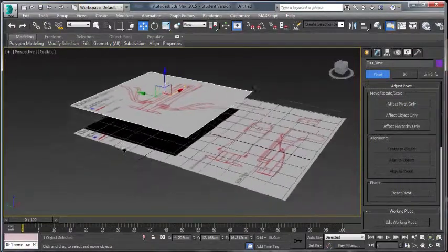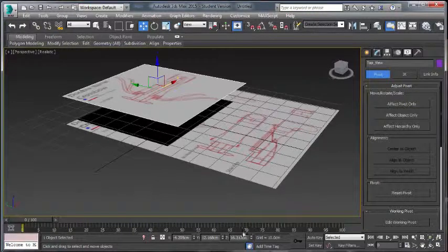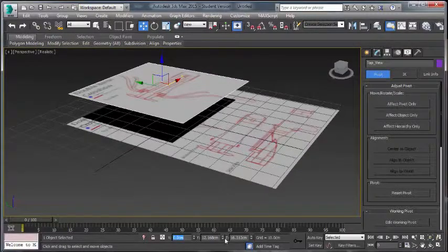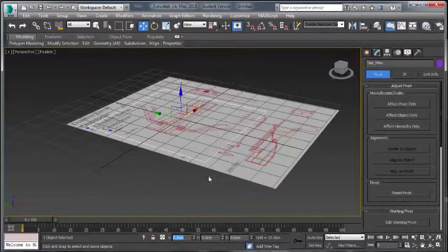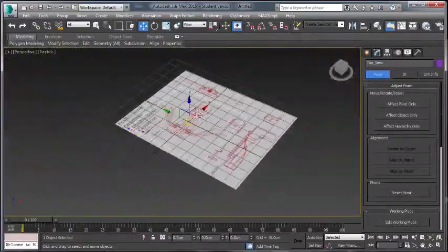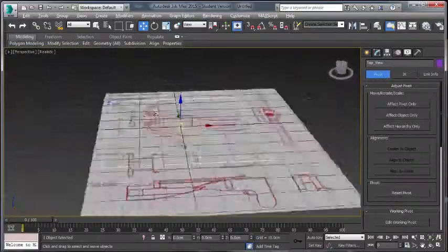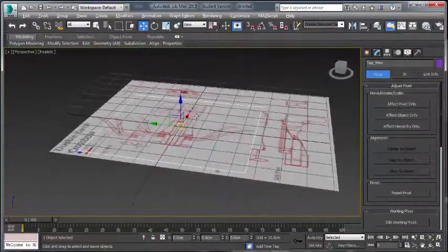Now when I go back to the move tool, I just want to center it into the grid. As you can see, our X, Y, and Z positions are a little bit off. The X is -4, Y is 12. We don't want any of these. We want to set it to 0 in the world axis. To reset this, you can simply type in 0 centimeters, 0, 0 with the move tool. But I'll normally just right click the little arrows to reset it to its original position. So now it's moved straight into position in our world orientation and movement, our transform I should say.